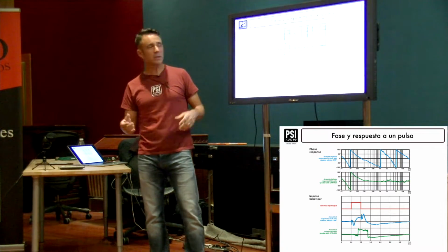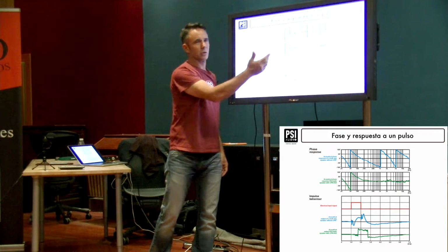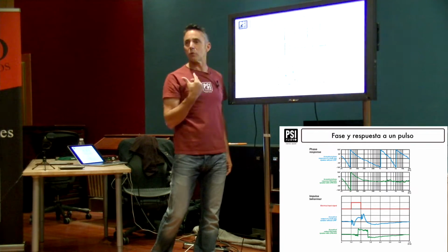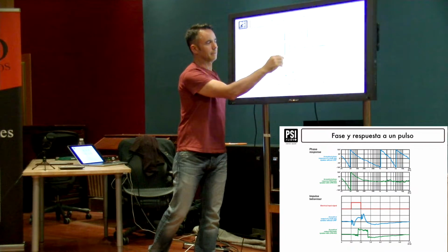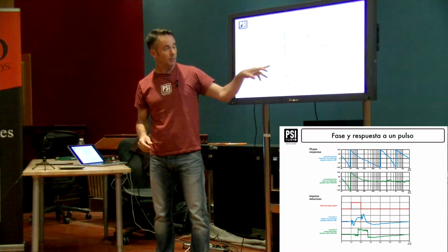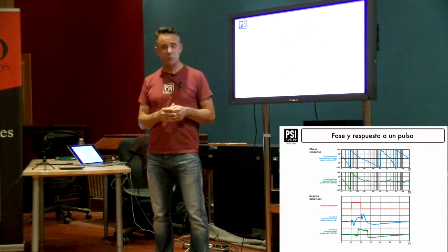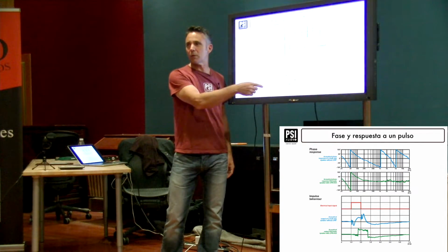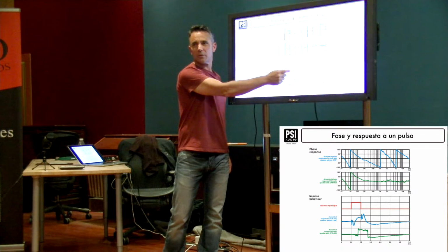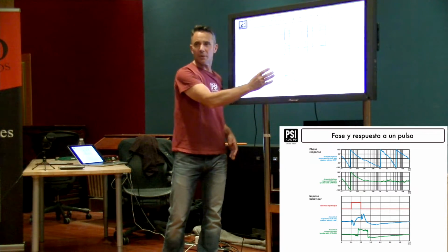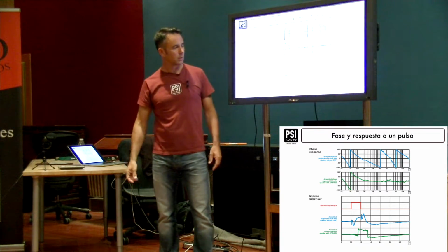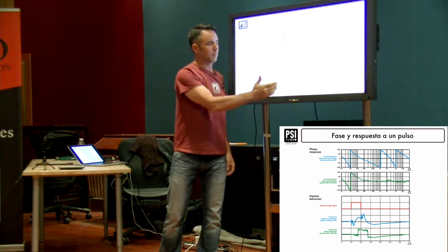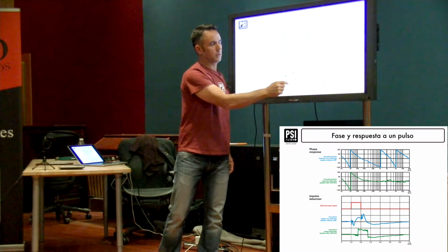The result of all this is if you put in a step response or a square signal, you don't get the perfect square, because in nature you'd need an infinite number of frequencies to fill in all these angles, but you still get quite sharp transients on a drum like this. With a normal speaker, first the high frequencies come out, the t, then the a comes a bit later, then the t stops, and then the a stops. So the high frequencies come and then the low frequencies a bit later. When you compensate phase, you wait until they're all back in phase, and then you start, and they all come out at the same time.